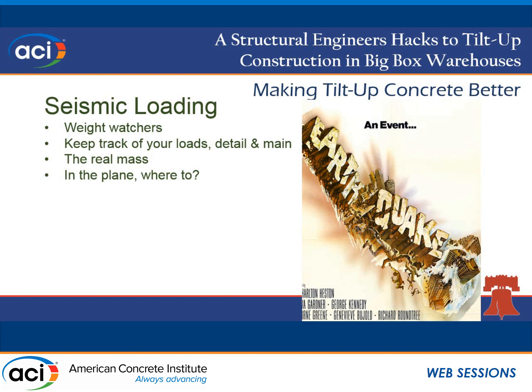The real mass of the panel has to do with, the other topic is in seismic. So you've got your mass of your walls, you've got your mass of your roof, and you're dealing with that analysis. If you look at the FEMA document that recently came out with flexible diaphragms, strong walls, it deals a little bit with an analysis for that, but the way I've always treated it is if you look at it as a single degree of freedom system, okay, your diaphragm is going to be humongously flexible, right? And so the period of your building and the mass that's associated with that is going to be almost completely in that diaphragm.